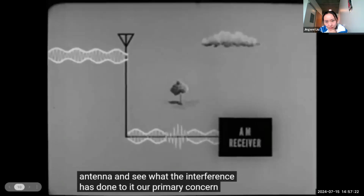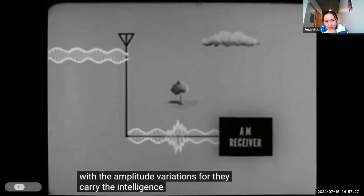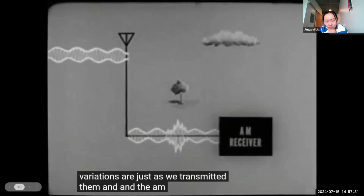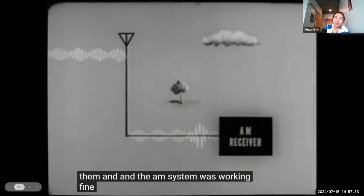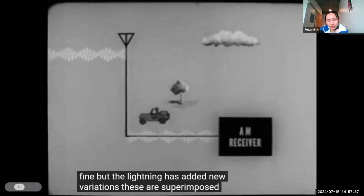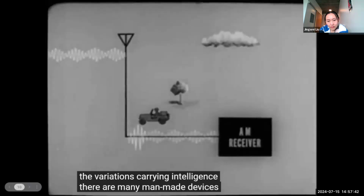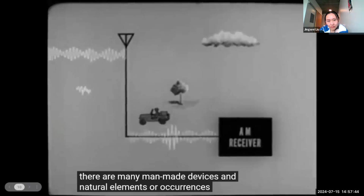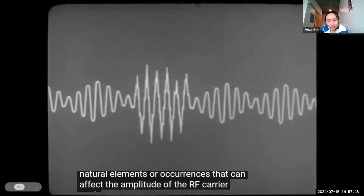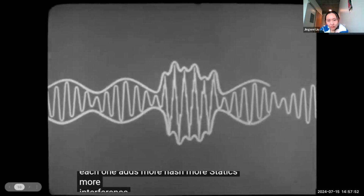Our primary concern is with the amplitude variations, for they carry the intelligence. To a point, the variations are just as we transmitted them, and the AM system was working fine. But the lightning has added new variations. These are superimposed upon the variations carrying intelligence. There are many man-made devices and natural elements or occurrences that can affect the amplitude of the RF carrier. Each one adds more hash, more static, more interference.